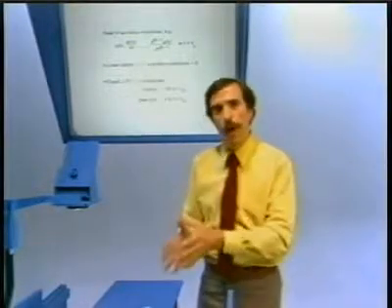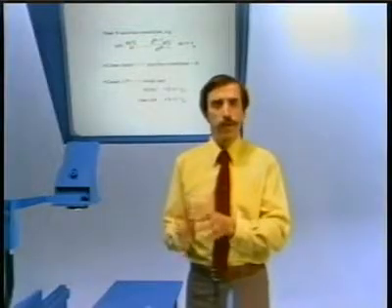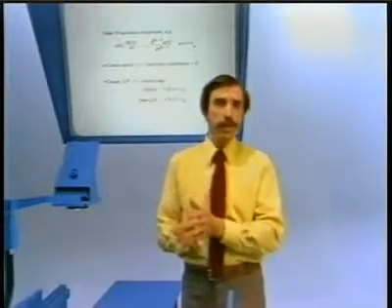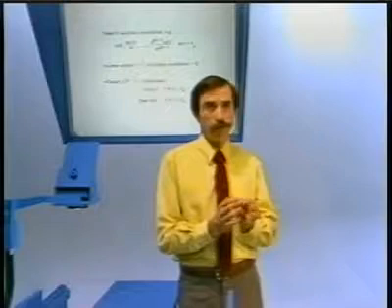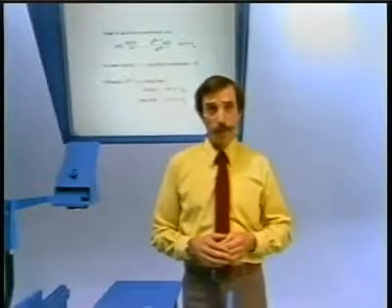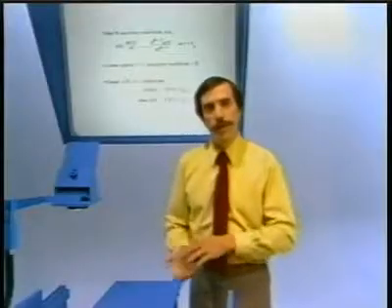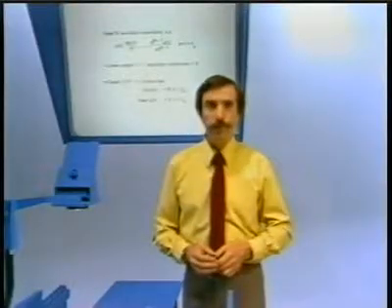will require initial rest. It's somewhat more difficult to see that if we specify initial rest, then that in fact is sufficient to determine that the system is both causal and linear and time invariant. But the essential point then is that it requires initial rest for both linearity and causality.